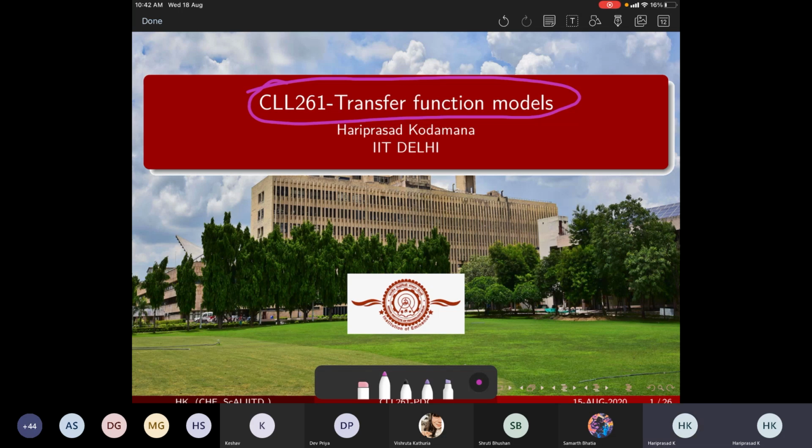So what have we learned till now? Our objective is controlling something. For controlling, we need dynamics, and in fact I would like to call it a model that sufficiently captures both steady state and dynamics. If you have that model available, then you will do a degree of freedom analysis and figure out what your manipulated variable is and what your disturbance variable is. We have learned up to that point.